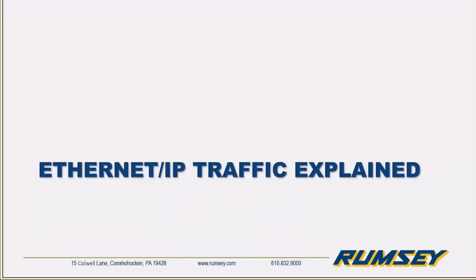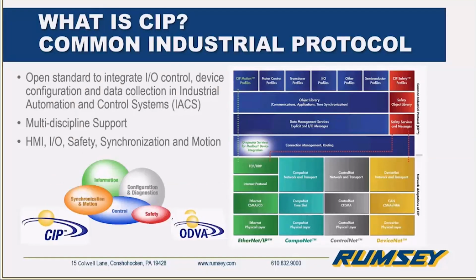What is CIP? You may have seen this. CIP, SIP, however you want to say it. CIP is Common Industrial Protocol. It's an ODVA standard for communications. It covers I/O control, device configurations, data collection, and industrial automation and control systems.